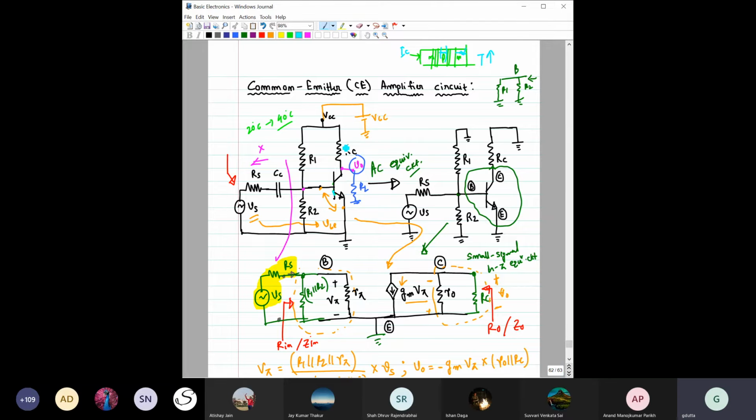And the same thing can also happen if you are using a very high power transistor, but the same thing can happen with the resistor as well, because IC is flowing through this resistance, right? So if you are using a low wattage resistor here, then before your transistor burns, this RC can also burn, right? So to avoid this issue, we should also introduce some negative feedback here. Okay, and the negative feedback can be introduced by introducing the emitter resistance RE, as we have discussed earlier, right?